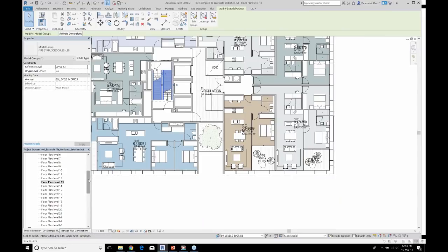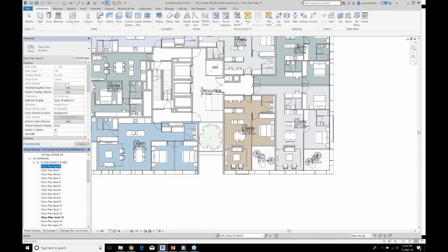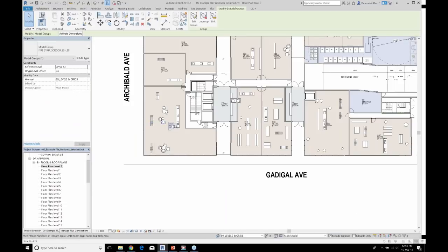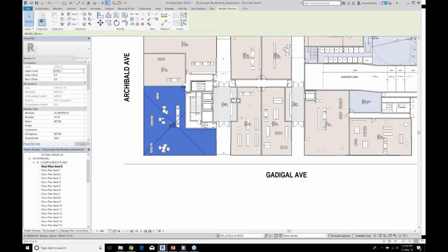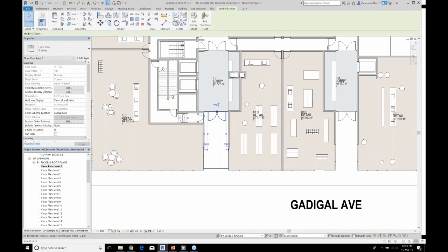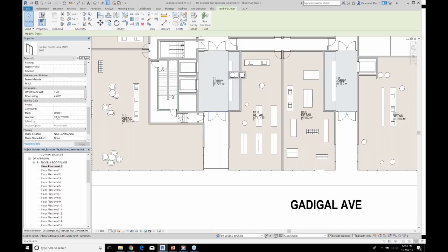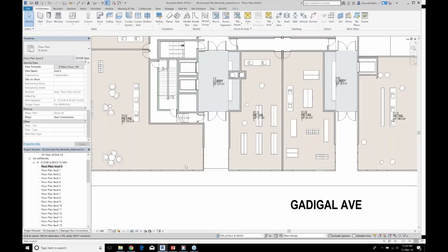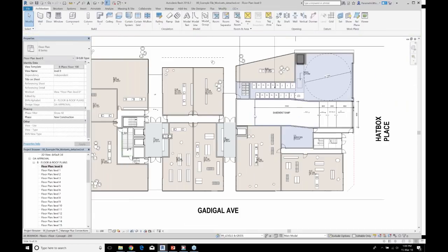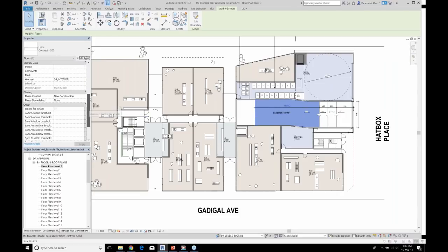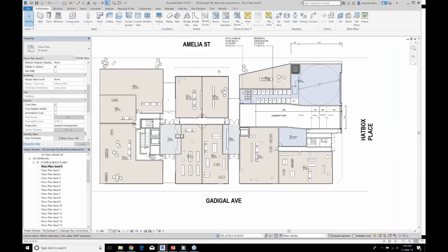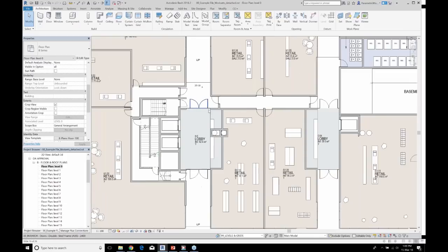If we look at, let's say, some other elements, we should see that the room's been assigned to the interior, doors, depends if this has been an internal or an external, but it's being picked up in interiors. So hopefully the majority of this has been assigned to all of the correct worksets.